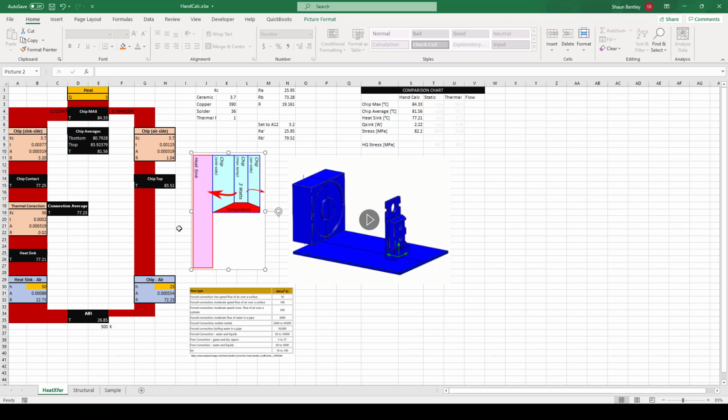That's the lowest thermal resistance to go this way. But then also some of it's going directly to the air. Some of it contacts that air directly. So we'll see these two main pathways that the heat takes. A lot of it goes left. I see about 2.2 watts of it goes left. Of that 3, about 3/4 of it goes left, and maybe about 1/4 of it goes to the right, out the side of the chip directly.